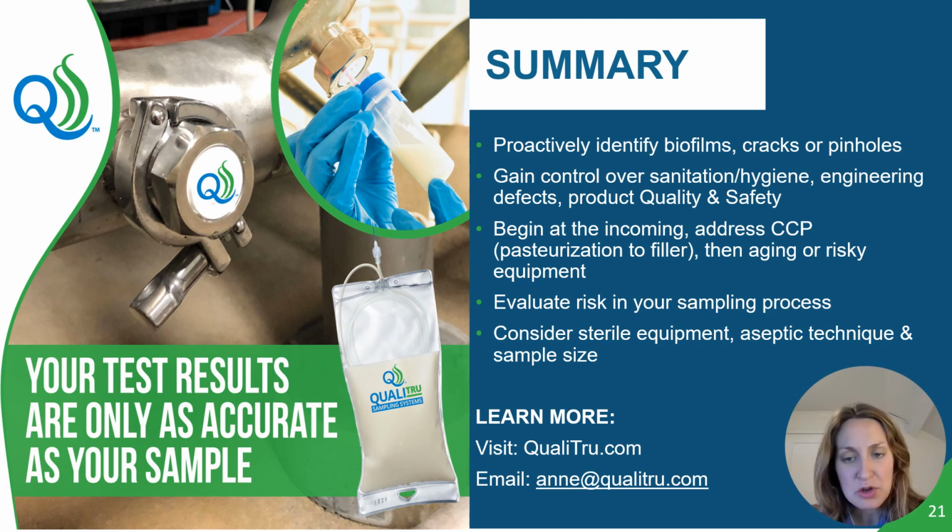Check your critical control points, really starting at the pasteurizer, and then any point between there and the filler where the product changes or it sits, or anywhere before that might be aging or have risky equipment or be highly specialized. So that would be any filtration. If you have a separator or a homogenizer, you want to be checking those as well.